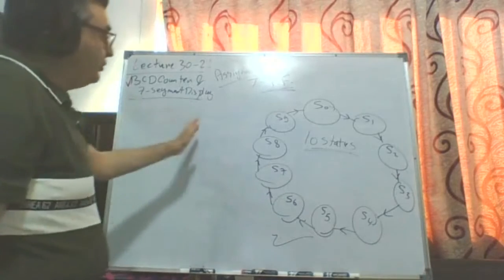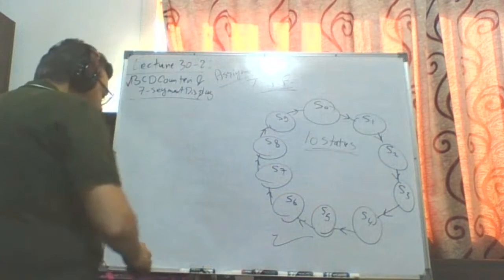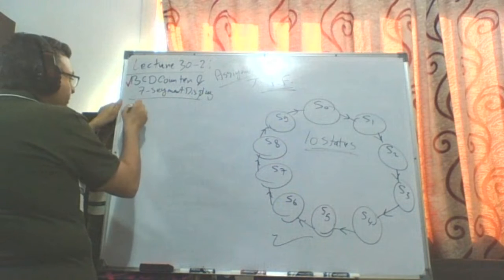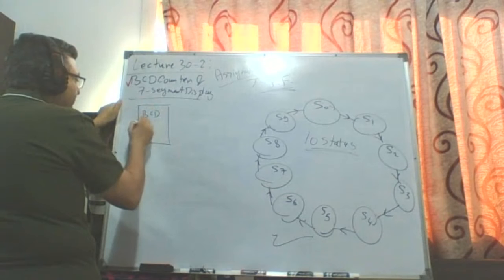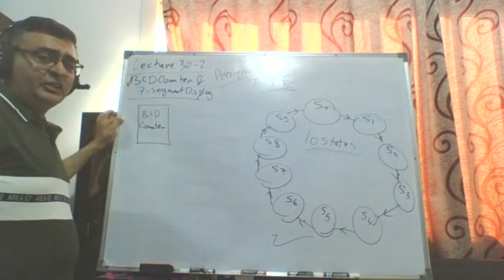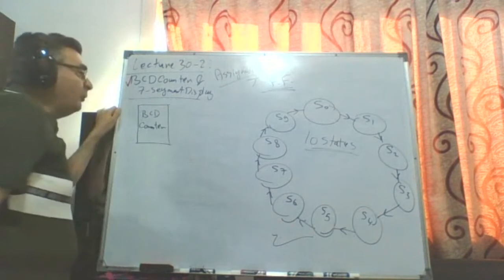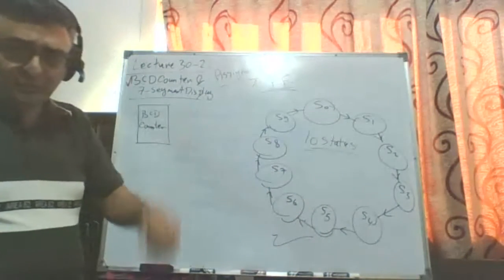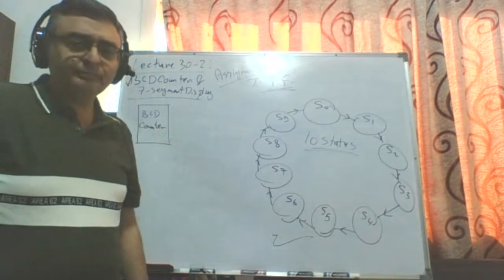After going through your steps of design, you will end up with a circuit, and we can have a block diagram for this circuit. Keep it as a block diagram for the BCD counter. If it is self-triggered, do I have any external input? The answer is no, but the circuit has an output. How many outputs? The outputs of the circuit will be the outputs of the flip-flops as you design it. Let me solve this for you in order to show the circuit.